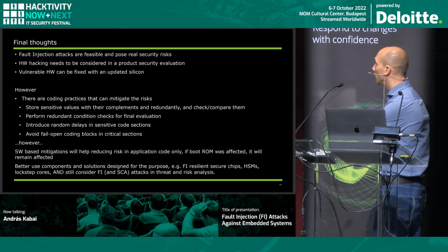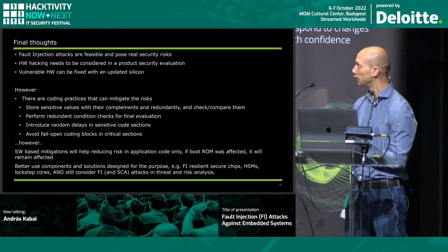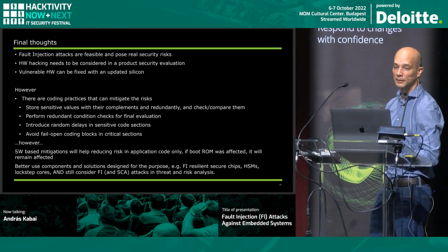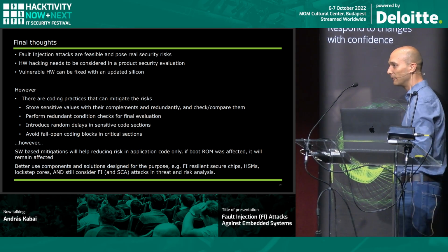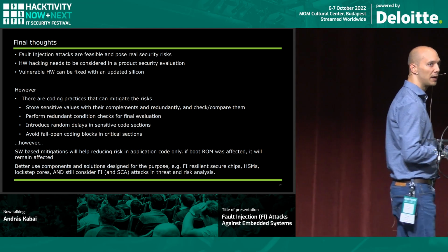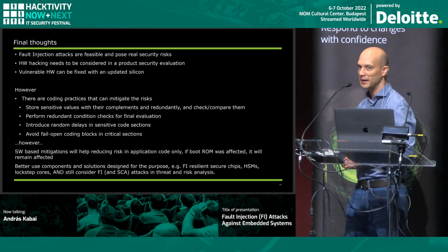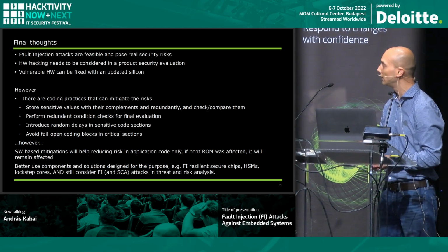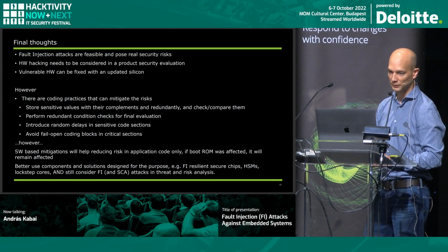And the final thoughts about the hardware hacking of these targets and the fault injections, especially the EMFI and voltage glitching, is that these are feasible and valuable attacks and should be considered by every vendor. And there is no secure device, no secure product with just only secure software. You could have the best and the most secure firmware ever, if your underlying hardware is vulnerable to such an attack, because in such case, fault injections are the one way to circumvent this kind of implementations in security in software.